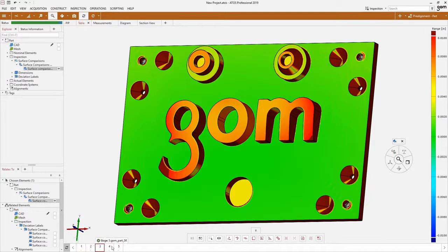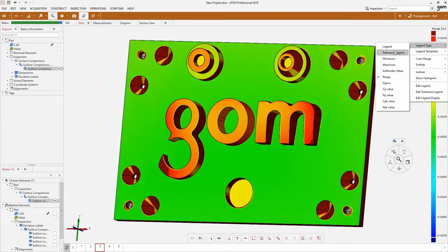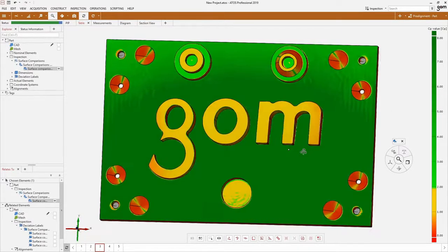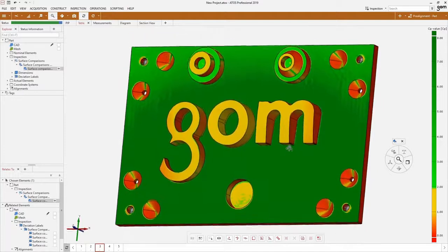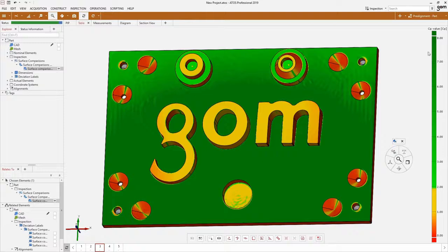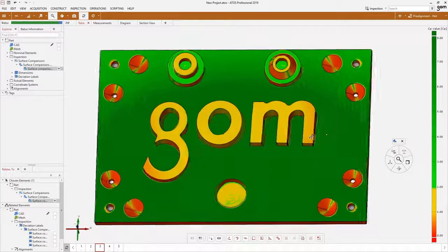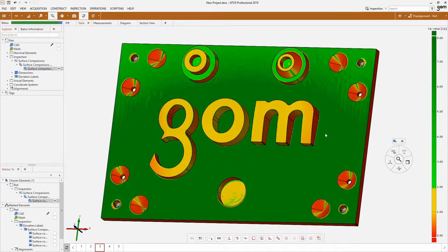So as I alternate between the timeline, you will notice that the color maps do not change. Just like we can change to range, other important graphs that can be pulled from this are, for example, the CP value graphs. Statistical process controls that can help an engineer figure out where the part is having the most problems. Utilizing these color maps, we could then observe all 5 stages within the same color map.